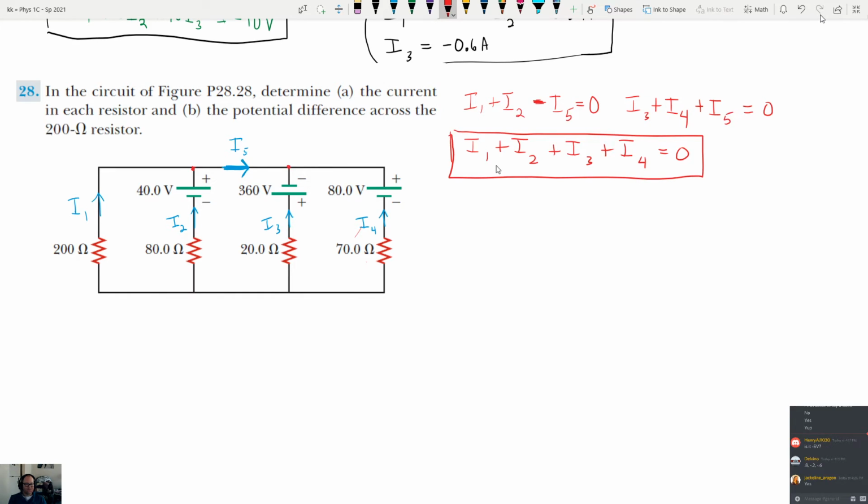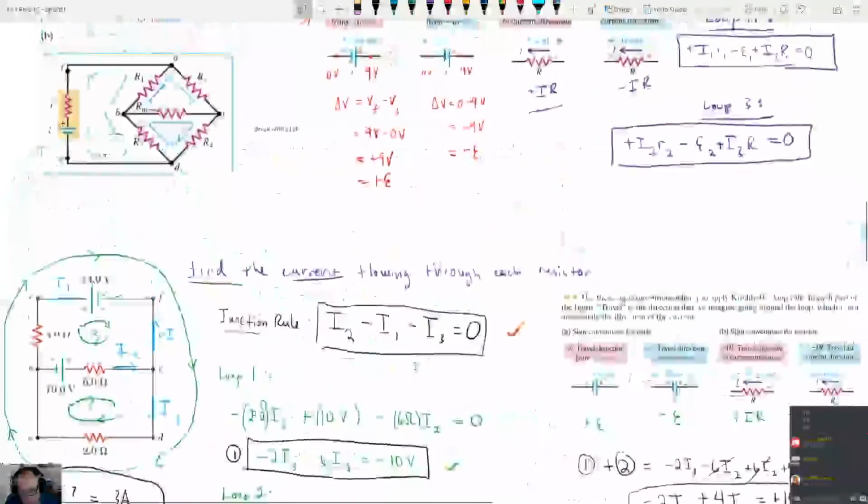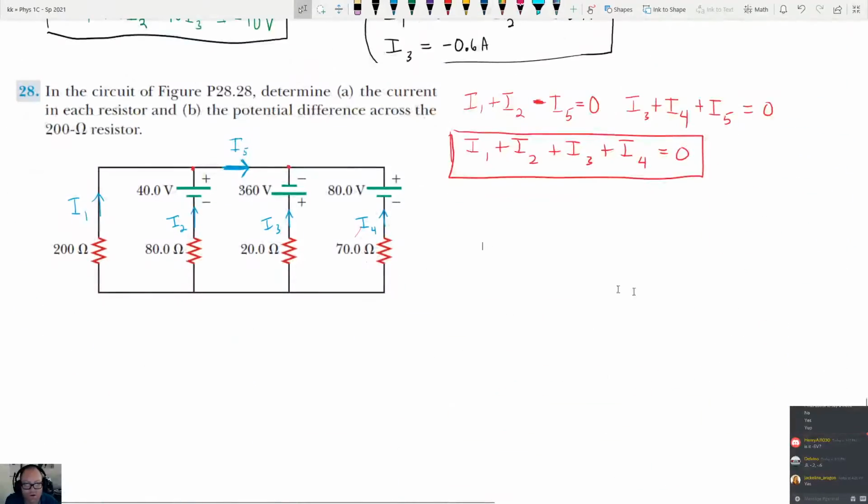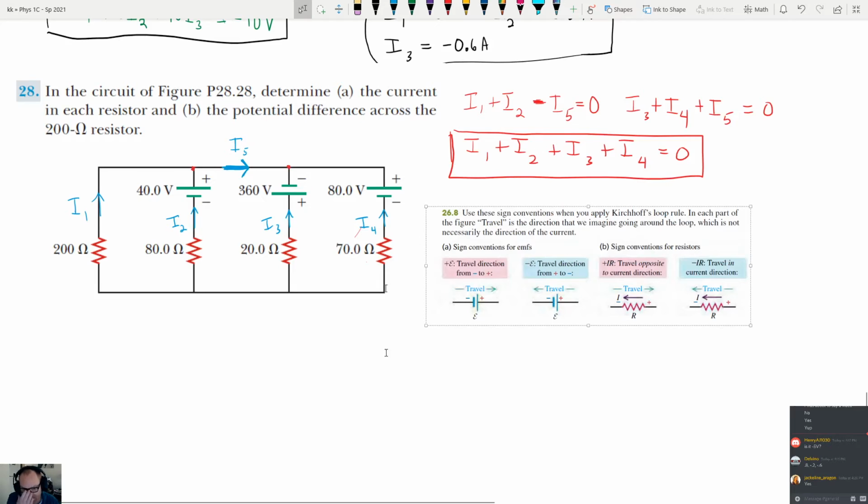Yeah, pretty much. In reality, you could put these 2 junctions together and it would be the exact same circuit. We could literally remove this branch and this branch down here and just connect these pieces, and it would still be the same circuit. So, anyway, try to solve it. You want to write down your loop. Do I need to copy-paste this down here? This doesn't hurt, in case you want to see it. Even this is just so hard to read. Okay. Give it a shot.